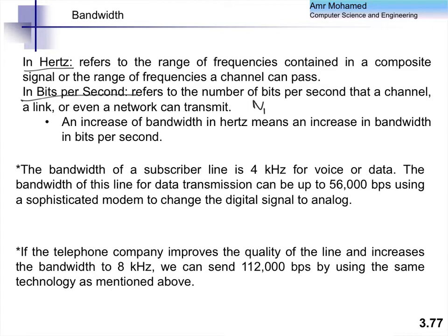So the bandwidth in terms of bits per second equals double the bandwidth, as we said, multiplied by log 2 of L. So it's directly proportional to the bandwidth in hertz, and it's logarithmically proportional to the number of levels that we can use to represent the bits.